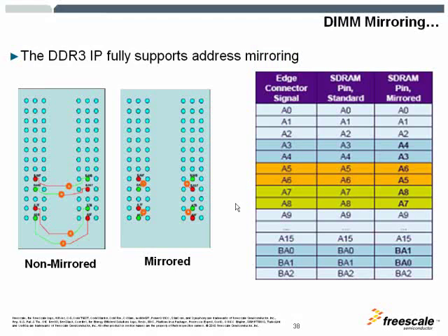The DIMM mirroring, or mirror DIMMs that you can buy: when you purchase a DIMM and the datasheet specifies that it's a mirror DIMM, it indicates that there are two chip selects or two ranks available on that DIMM, and the routing between the two ranks is done so that the stubs and traces are reduced by switching some of the signals so there's no cross connection required, and that would improve the signal integrity.